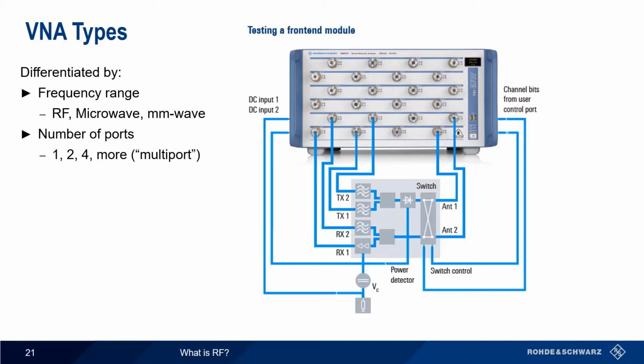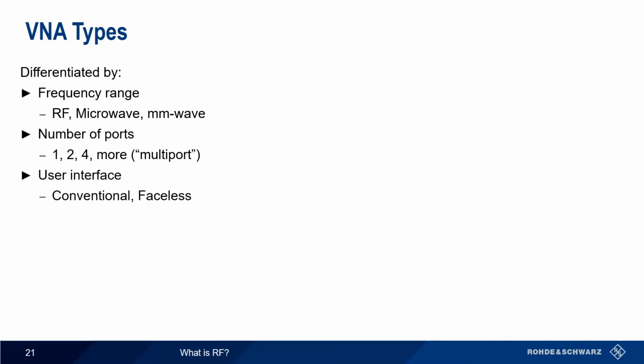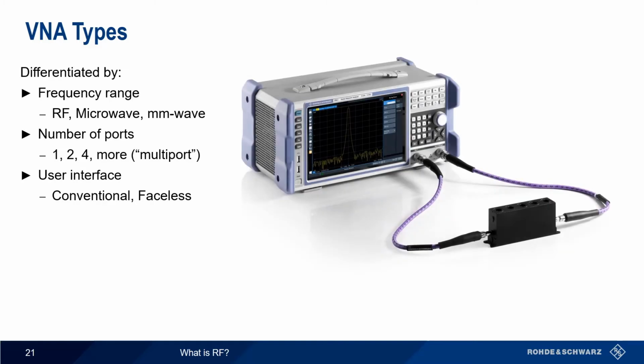The final VNA classification is whether the instrument has a built-in user interface or not. Often, faceless instruments rely on the processing power of an external PC and are generally mouse-driven. Instruments with built-in screens and buttons are completely self-contained and often easier to operate on a bench.